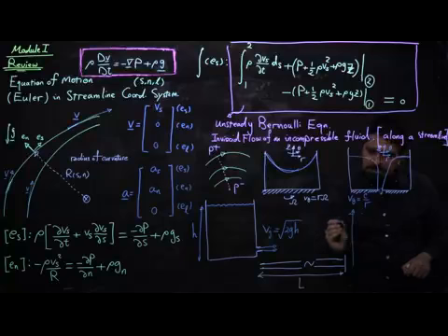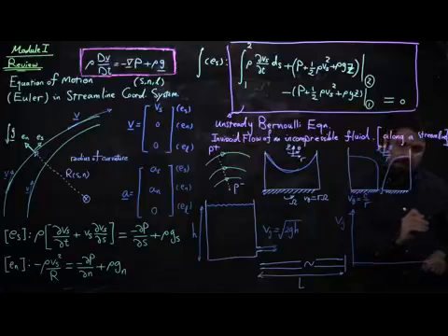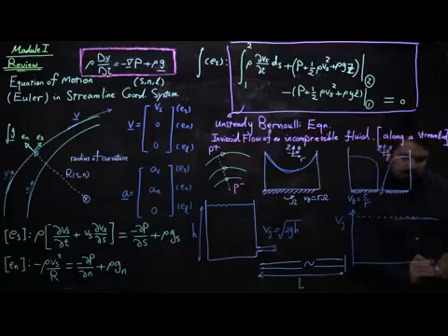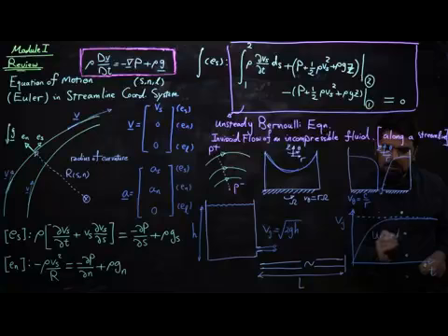Velocity of the jet that comes out of this transient problem asymptotically reaches the square root of 2gh, which is the steady state result if we wait enough in time. But at early times it shows a linear increase with time, and we found that this can be captured by the tangent hyperbolic function, and this all came from solving the unsteady Bernoulli equation for this problem.